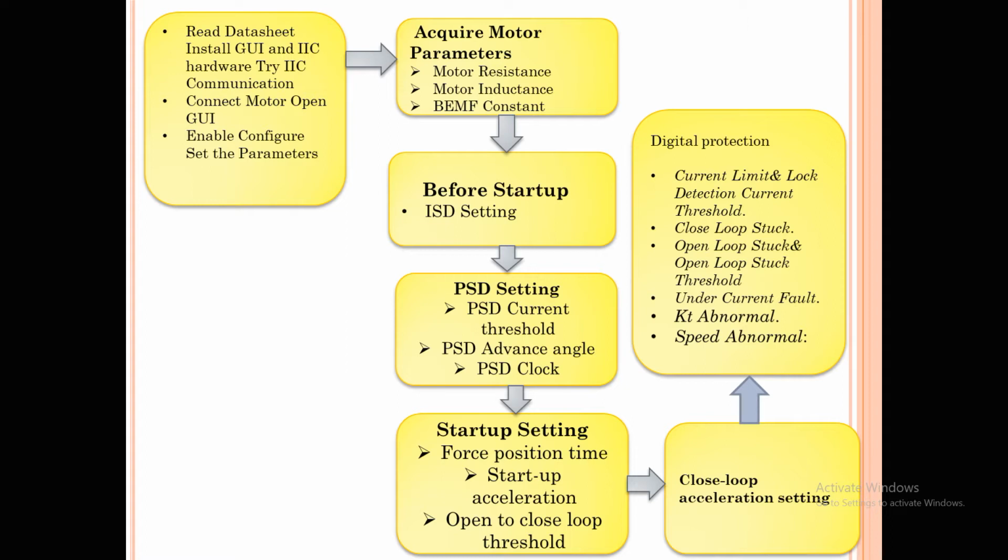In some cases, some tolerance comes in, so let's take an example. Say you design a motor with a resistance of 2 ohm, an inductance of 5 millihenry, and a motor velocity constant value of 420 millivolt per hertz. If you go for mass production, sometimes when you wind with an automatic winding machine, the layering is improper due to manufacturing issues. Sometimes parameters may vary, but how much they vary depends. So 10% tolerance is acceptable.